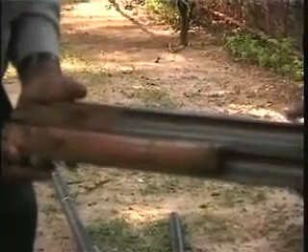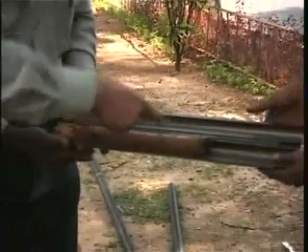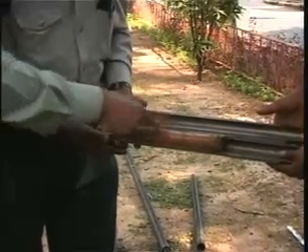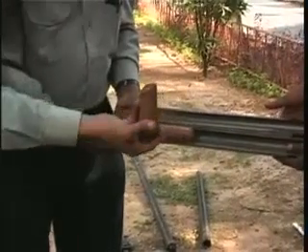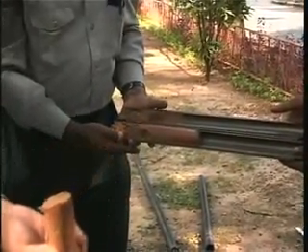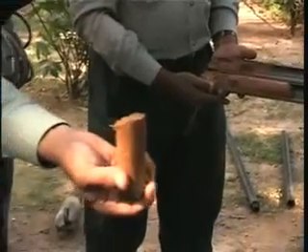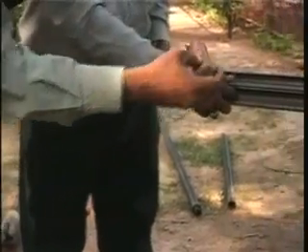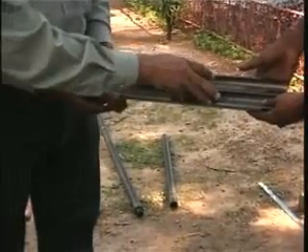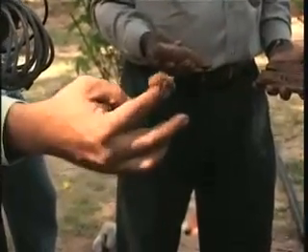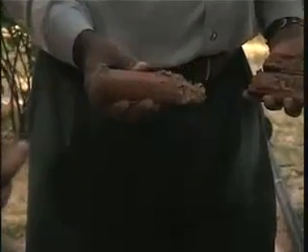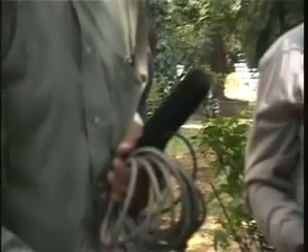If you recall, this is the bottom end of the sample, and that is the top end of the sample, and you can see that the sample was moist near the top, and it was becoming dry as we went downward. So this has a lot of sand and silt and other fine-grained soils. It has some cohesion as well, and that's how we identify the sample. And this is the sample which is near the bottom end of the sampler. Okay, so this sample is saved for grain size distribution and finding out the natural moisture content of the specimen.